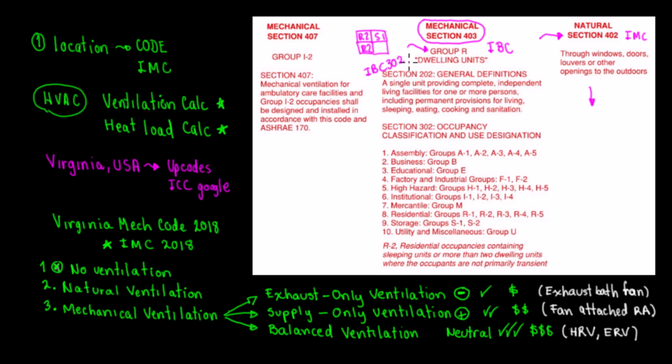In that section, you have this classification. So where are you going to provide ventilation? You're going to provide ventilation depending on the space where you want to ventilate, because you're not going to ventilate that storage room, right? There are not so many occupants.